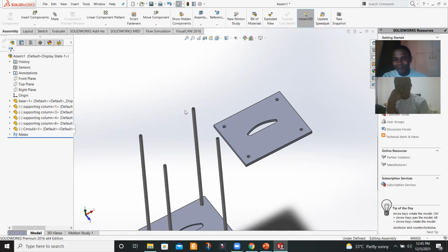Along the line, when I was teaching parts, I taught how to transfer a sketch from one part to another. I did that when I minimized the window and transferred a sketch to the next part. Now, if you don't do that here, I can bet with you, if this O and this O are misaligned by 0.1 mm, Solidworks will raise an error and tell you that it's not possible. So if those 4 O's were not properly aligned, and the interesting thing is that in the real life machine, it wasn't aligned.